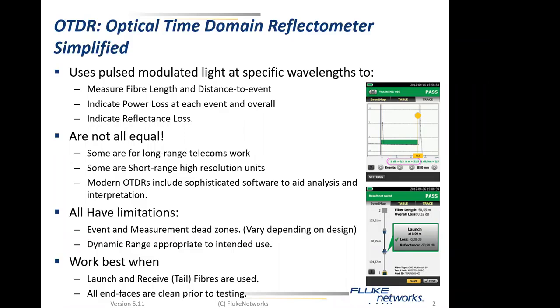And possibly most importantly, all end faces need to be clean prior to testing. And I apologize if this is something that you hear on a very regular basis, but we still see an awful lot of people using OTDRs and getting questionable results, and the questions relate to the condition of the connectors that they are plugging into. So we need to bear that in mind.